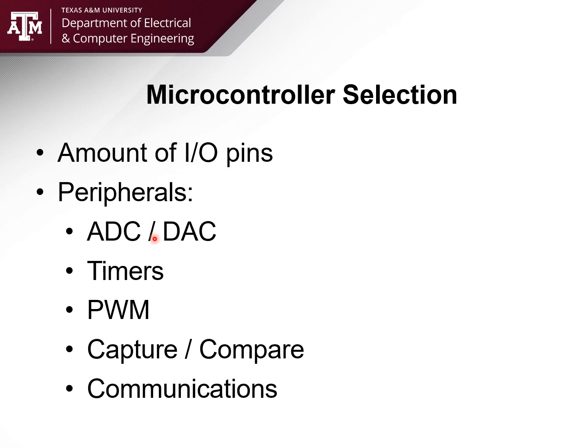Peripherals to consider: analog-to-digital converters, digital-to-analog converters, timers, pulse width modulation, capture compare, and communications. Capture compare is usually dealing with time, pulses basically coming in. Communications, for instance, we were talking a moment ago about UARTs and Ethernet. What do you need? You want to make sure that your microcontroller supports the actual communication interfaces that your system will need.